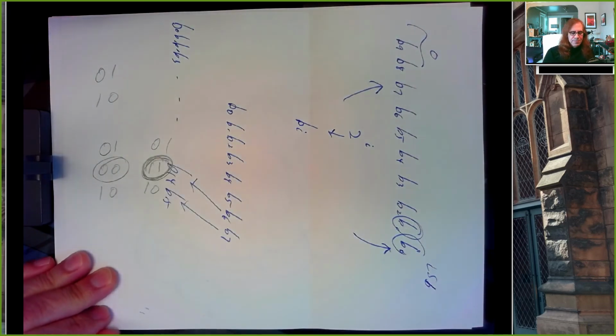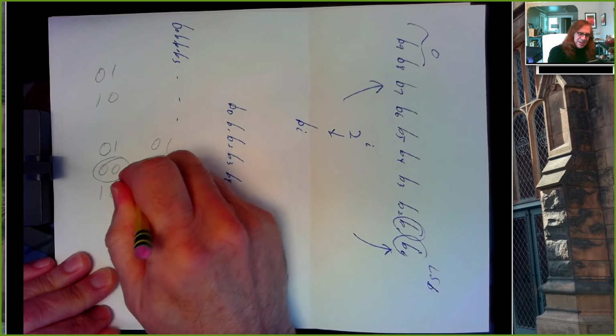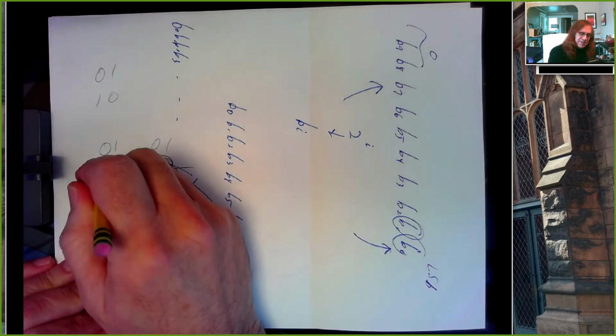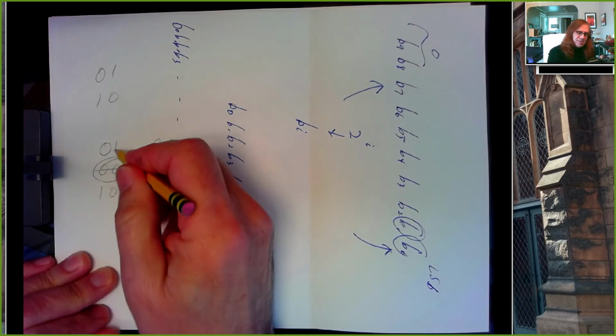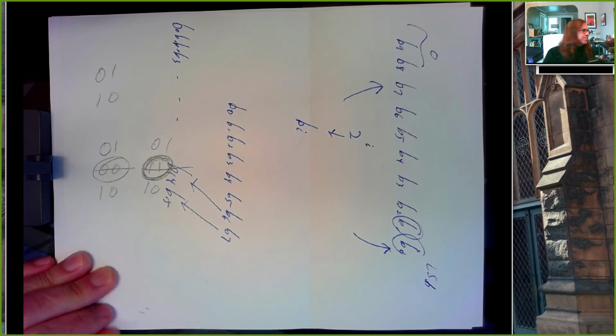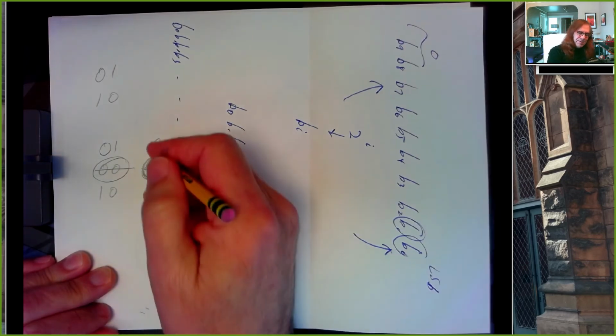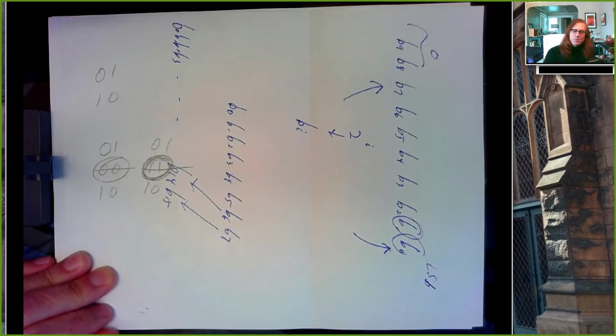But if this is recognized as an invalid state, and this is an invalid state, then we can build a circuit that won't inadvertently do something wrong when it goes from, say, state 1 to state 2. So if we code all of our states in such a way that only one bit is allowed to be a 1, then if we go through these transient states in between, they'll just be considered invalid states.